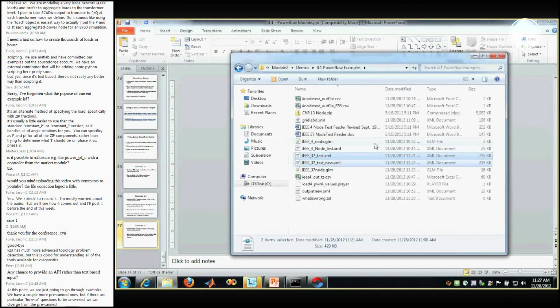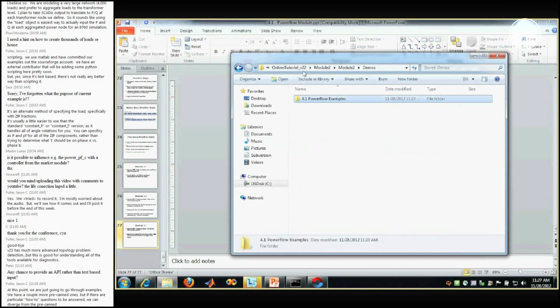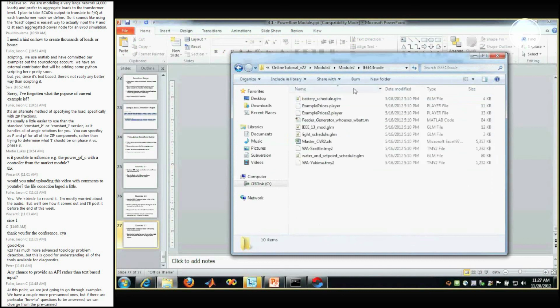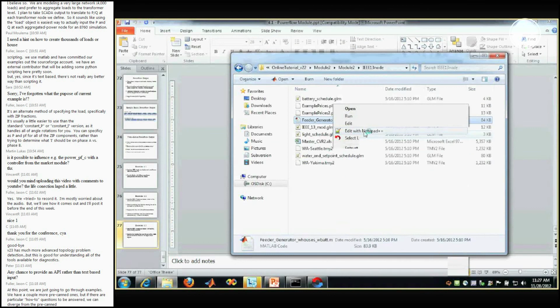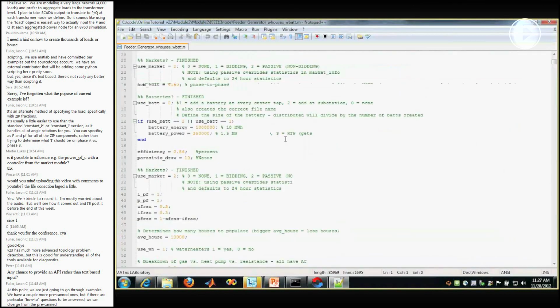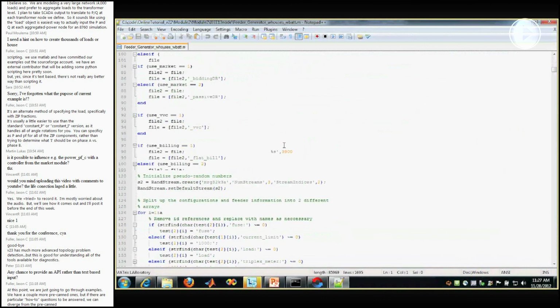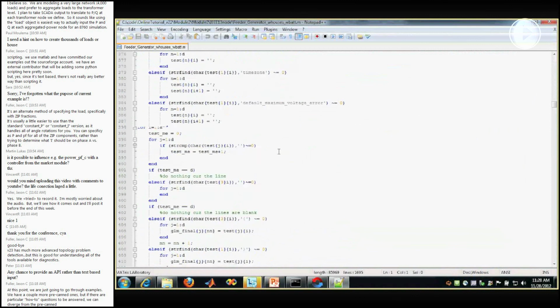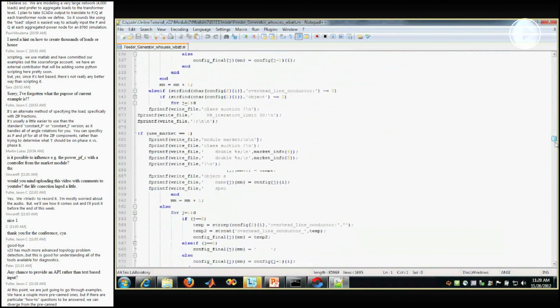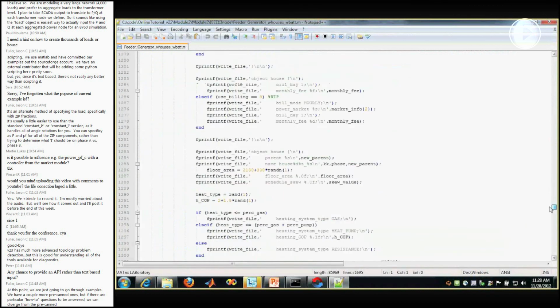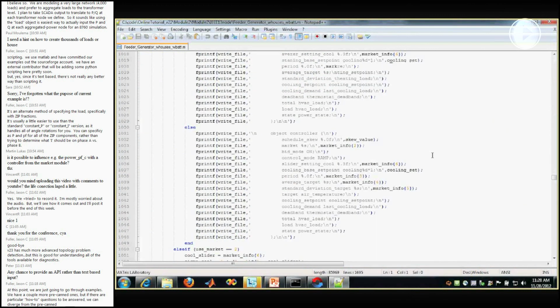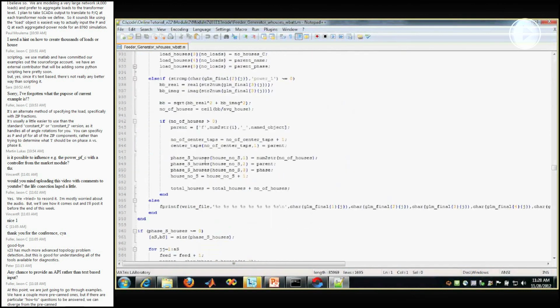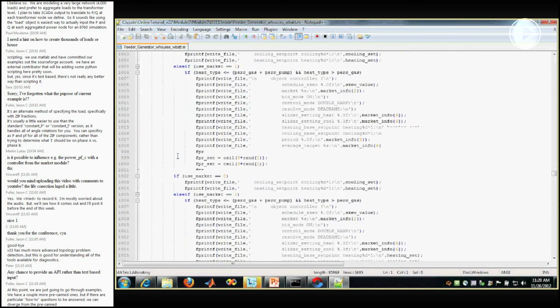So if we load up the system, I don't think it's in this folder. I think it's in a different folder. There's this particular one. Going back to an earlier question, this is how we do the larger generations. This is a much earlier form of the script than we currently use. There's a much better version underneath the taxonomy feeders folder that Jason mentioned earlier. But this is how we've generally populated feeders or created more advanced systems with a lot more houses in a deterministic way, with a MATLAB script that parses out the text file and then generates a new text file.